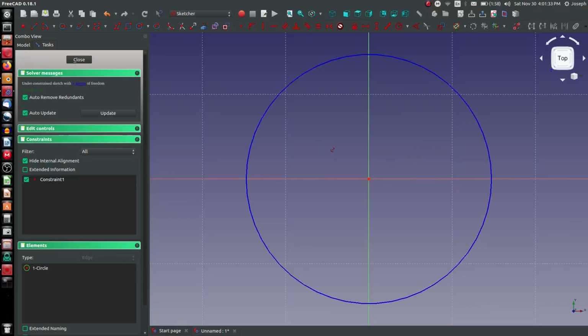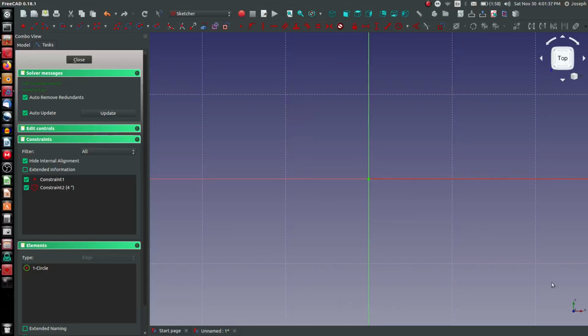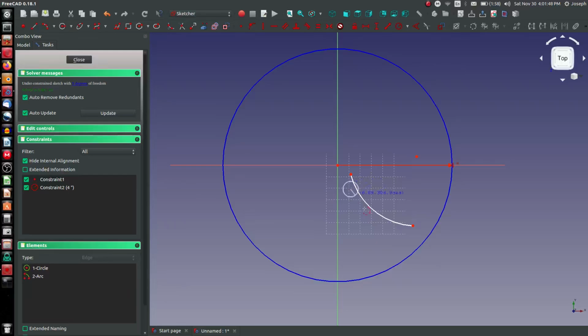I've got currently settings for radius, so we'll give this a radius of 4, which is the diameter of 8 we gave before. I can go back to driving geometry, and I'll go to my arc by three points. We're going to create 2. Then instead of concentric, we'll merge these points to get a concentric relation. And as before, highlight 3, horizontal. Drag this to a more ideal location.